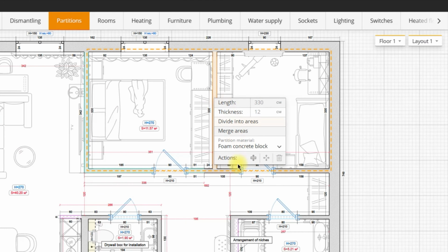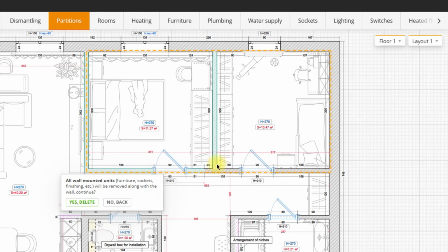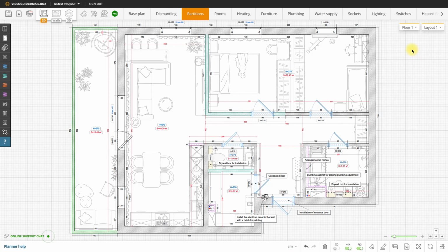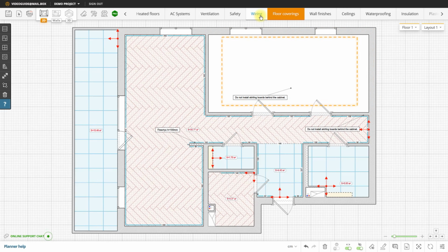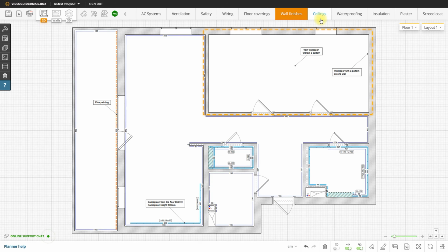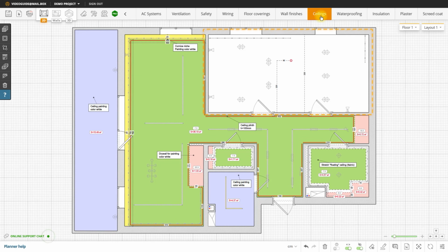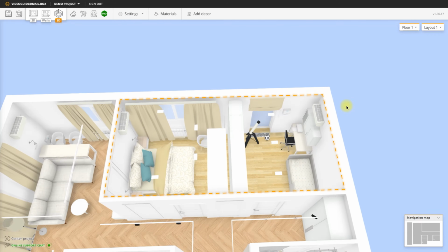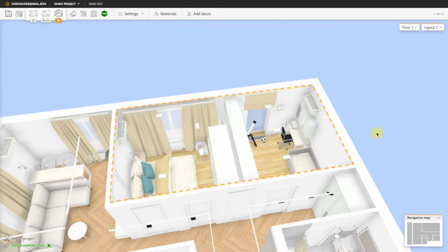And then you delete a wall. The software will automatically reset related elements like ceilings, floor zones, and wall finishes. This isn't a bug. You've essentially created a new room with new parameters, and prior data no longer applies. Try to avoid this to prevent doing work twice.